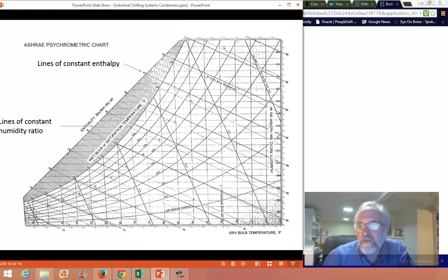So if you remember the psychrometric chart from thermodynamics, it's a way of looking at mixtures of dry air and water vapor. It's very busy, but the main temperature scale is along the bottom here, and it's in Fahrenheit. So these small numbers you can read sort of vertically. So here's 80, 85, 90. These vertical lines are the dry bulb temperature. Horizontal lines are humidity ratio. So it's the mass of water relative to the mass of the air.